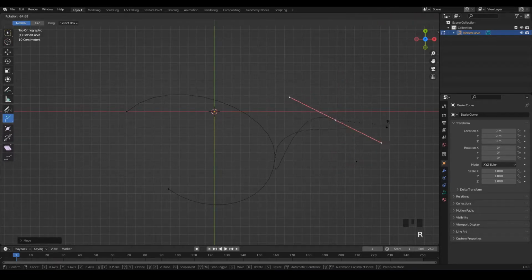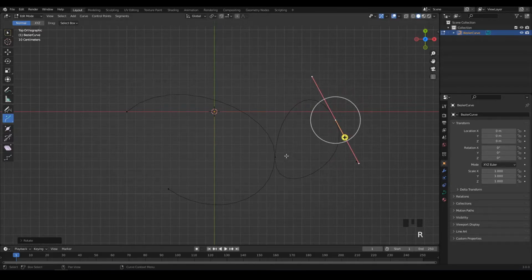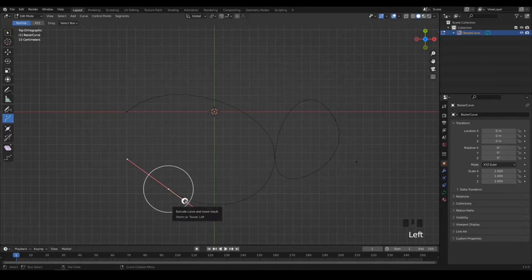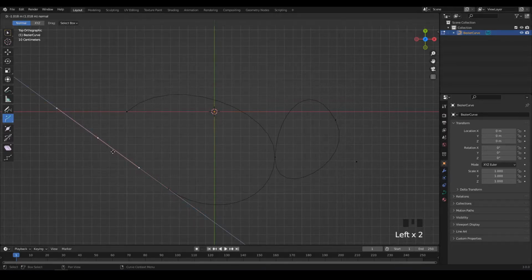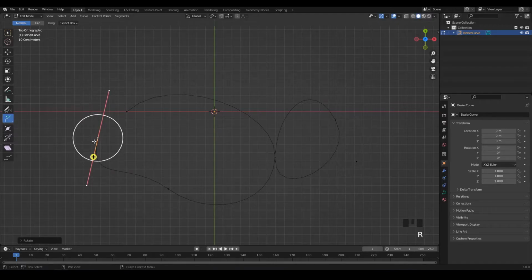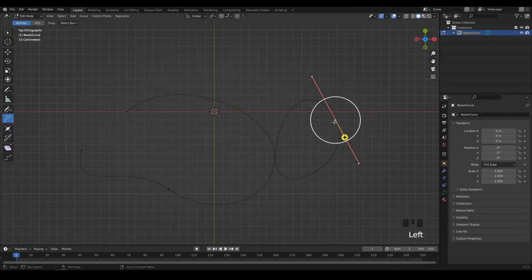This has a really strange shape because I've started the extrusion from a point in the middle of the curve, but if I do it from the edge of the curve, this is adding a normal point to the curve. I'm gonna delete this point using the X key on my keyboard and selecting vertices in this drop-down menu, and this has deleted the point.